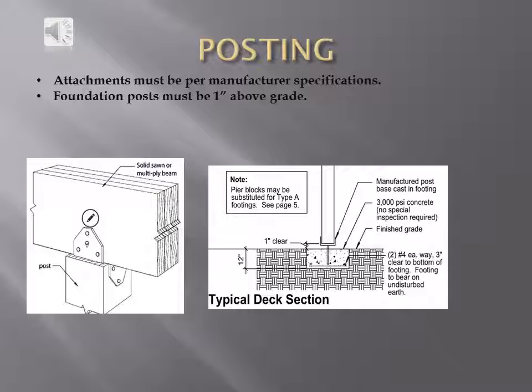Posting. All post attachments between the post and the beam must have a hanger per manufacturer specifications. All foundation posts must be 1 inch above grade. This allows for adequate ventilation and prolongs the life of the wood.